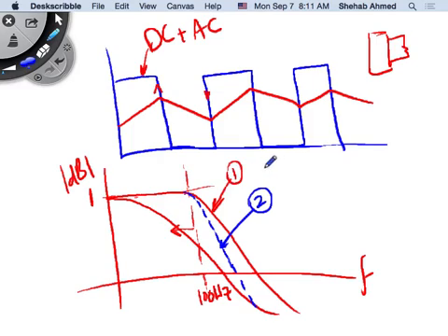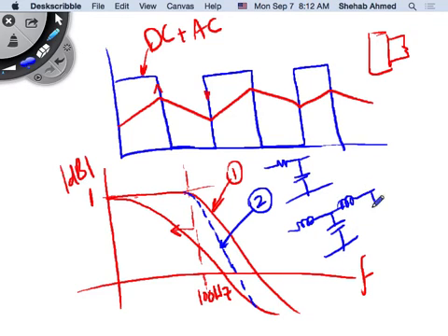This can be a simple RC circuit, for example, the red one, and then this blue filter, because of the quicker roll-off, you definitely need to control things better than just a simple time constant of an RC circuit. So this is maybe an LC, a second order filter, or maybe you can add another L here, another C here, and you create a fourth order filter.